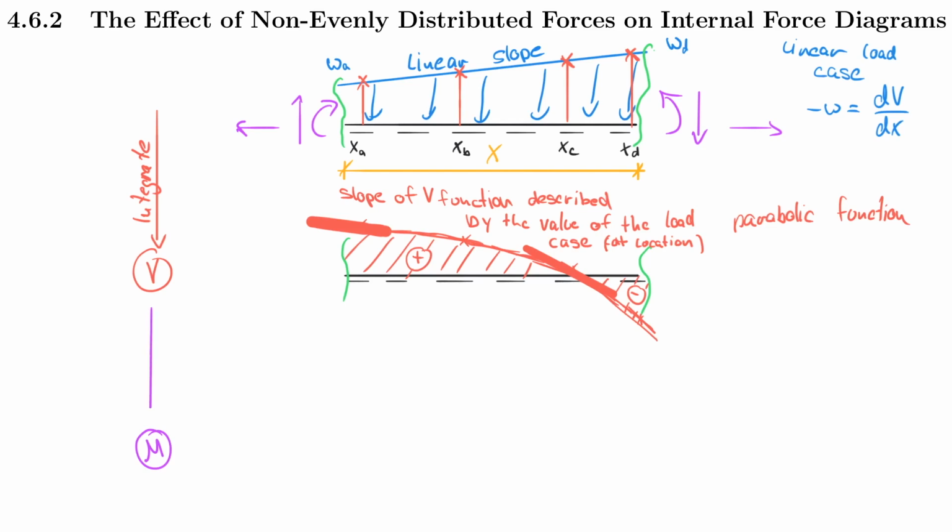So let's highlight that one more time. So we integrate. And if we integrate, we know that at this location we must have a local maximum or minimum. So when we integrate the shear force function, then we go through 0 right here, and therefore we must have a maximum in our moment diagram. So let's go ahead and draw the free body diagram, or a cutout of that, and let's include that we now have to consider a local maximum or minimum. In this case, I'm very certain that it's a maximum for the very same reason that I used before.